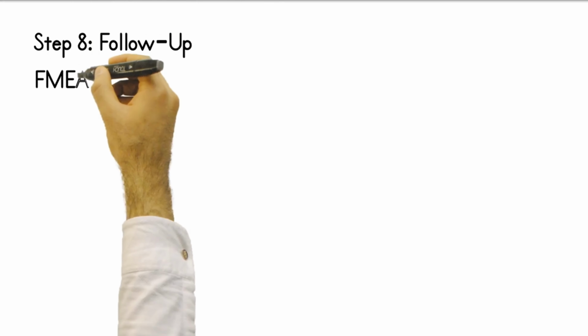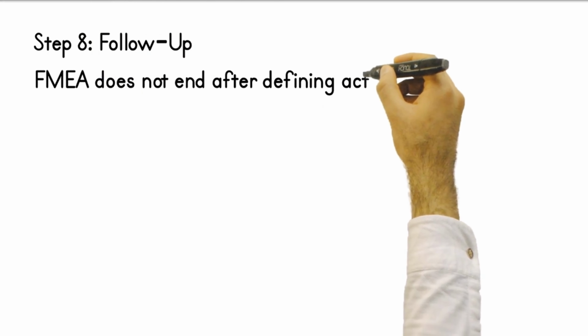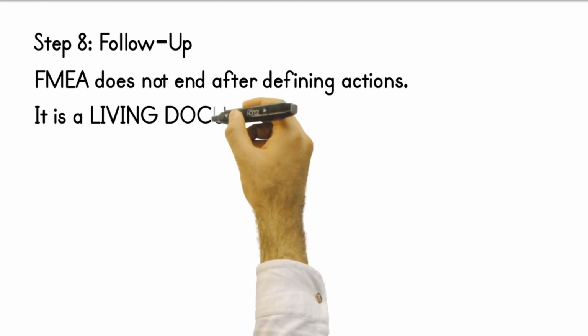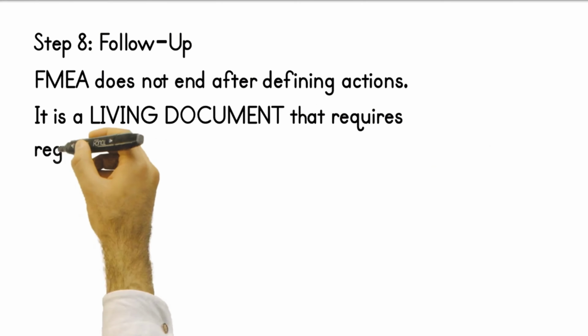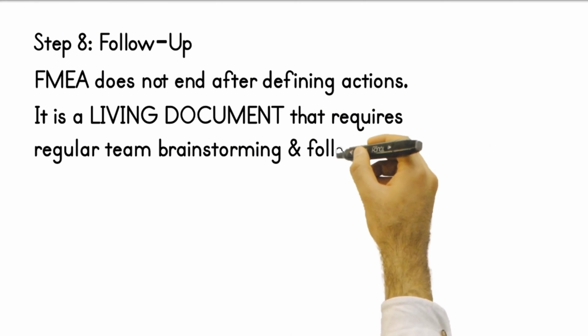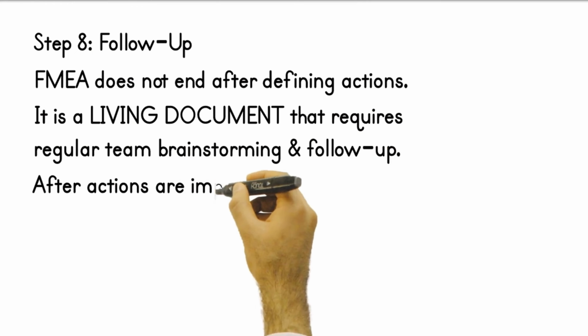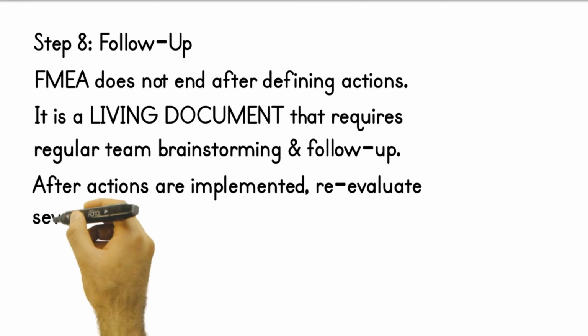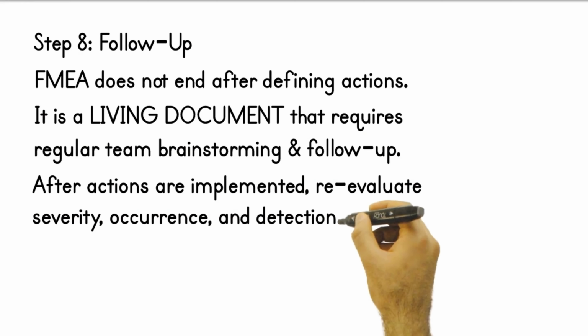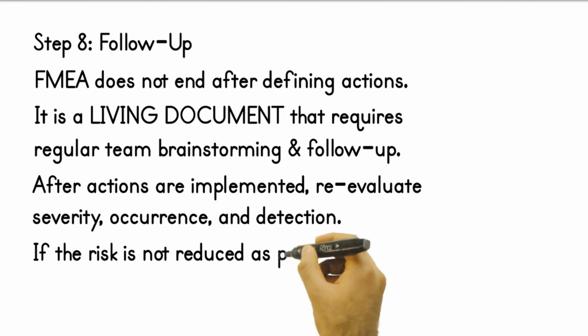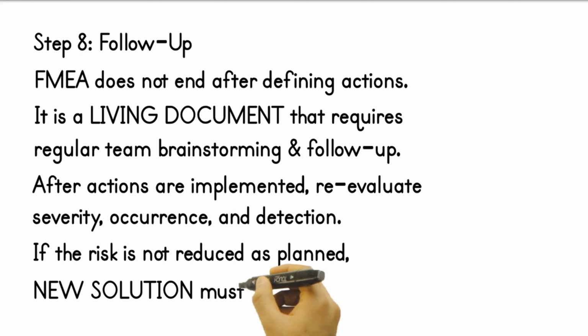Step 8. Follow-up. FMEA does not end after defining actions. It is a living document that requires regular team brainstorming and follow-up. After actions are implemented, re-evaluate severity, occurrence, and detection. If the risk is not reduced as planned, new solutions must be considered.